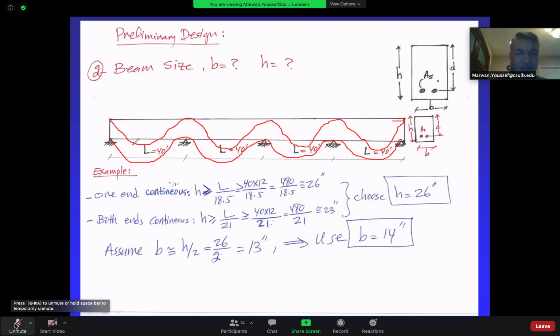So I come here for this first slab. Look at the tension. Tension is at the bottom. It's being stretched. So I need to put the steel at the bottom. So the steel for this slab is going to be this yellow line. Okay? What about over the support?